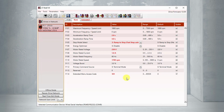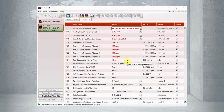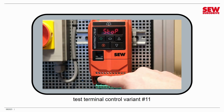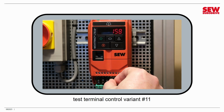So we need to go back to the extended tab, re-enable real-time edit mode, and I'm going to change parameter 15 to 11, which is our second control variant that involves push buttons. That's all I have to do here. I'll turn off real-time edit mode and let's go push a few buttons. All right, first thing we have to do is turn the stop switch to the normally closed position, and we'll try pressing the start forward button and turn the pot up to make the motor turn.